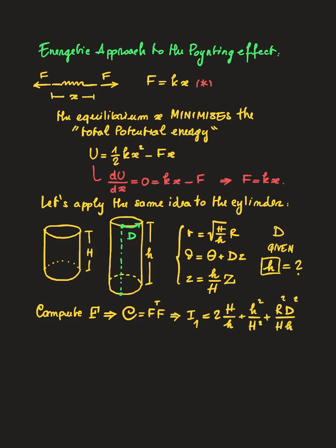Well, at this point, you can use the idea of energy to compute the strain energy. And assume, for example, that the material is simply Neo-Hookean. So let me take a Neo-Hookean material, and for a Neo-Hookean material, the energy W is just equal to mu divided by 2 times I1 minus 3, okay? Once you have the strain energy, in this case mu is the shear modulus and is always positive, you can compute the energy.